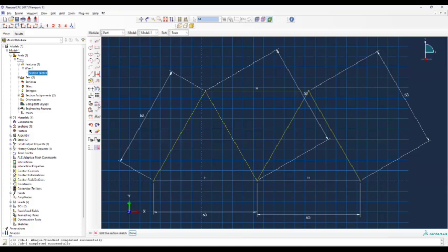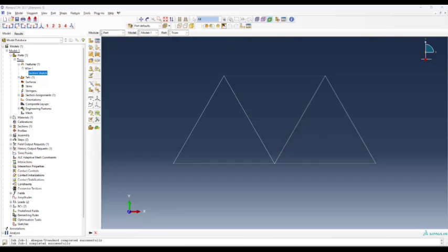We can assign constraints. We can assign dimensions to create our part. So based on, let's say we want it to be fixed, we can prescribe that. We can prescribe it to be coincident, two points coincident, some points or some lines perpendicular, horizontal, etc. That's very useful. You can even dimension parts. If you have already assigned a dimension to a part, just click this right here to edit it. You make it longer, shorter, whatever you like. But that was the first step, just creating the part itself.